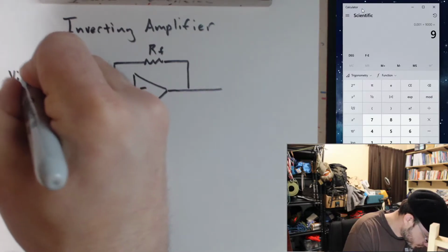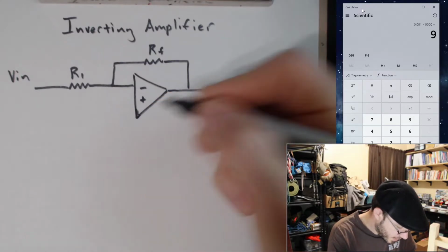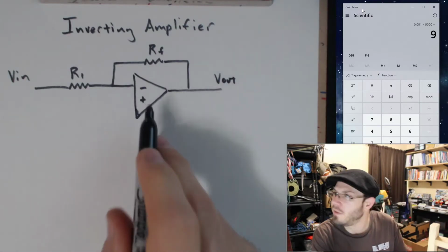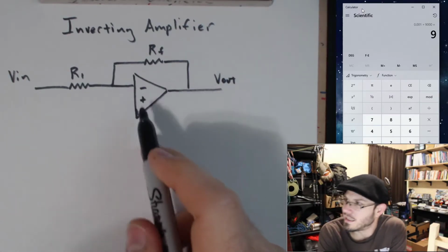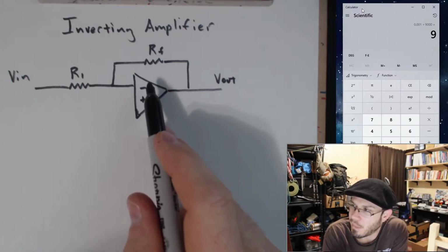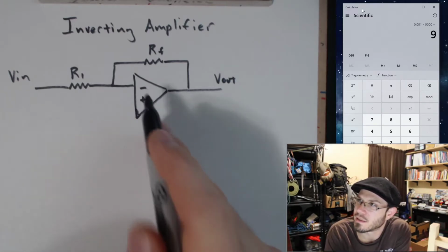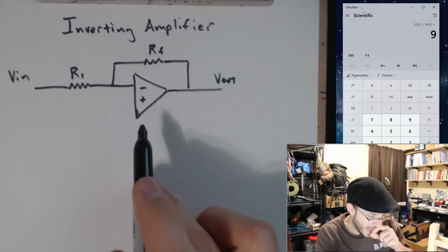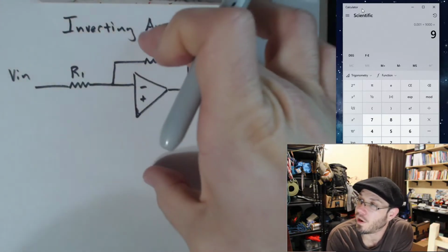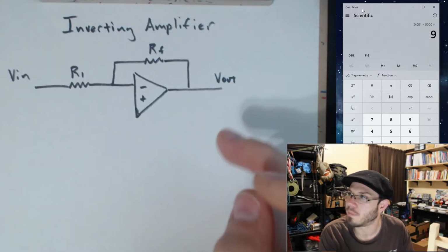So, Professor, that's the schematic symbol for an op-amp? Yep. The only thing I'm leaving out of it for all of these examples and circuits is the positive and negative rails. So how you power this op amp, I have left out. I am working off of the assumption that I am powering it and I'm keeping my inputs and outputs within those power rails.